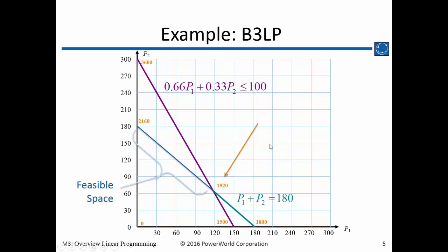The other thing is that the objective function for each operating point along here is shown by the orange number here. So again, if we're ignoring for the moment, because we're looking at this in 2 dimensions with 2 marginal controls, 10 times the output of generator 1 plus 12 times the output of generator 2 is the total cost. So if we get all of our power from the expensive generator, it has a cost of $21.60.